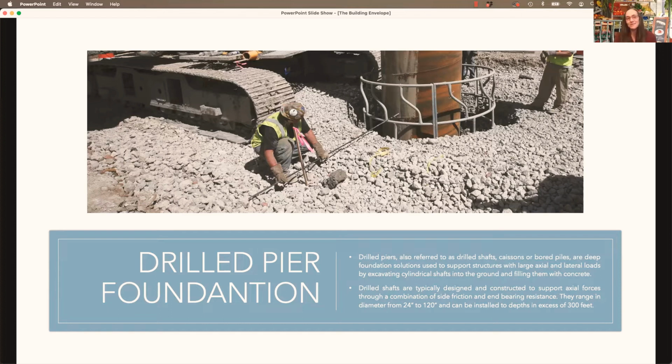I don't know why, but I think they're actually okay. If you float the floor, that just means that you're going to have a framing system on top of the slab that elevates the floor up a little bit higher. Typically, your basement will be a little bit warmer because you can insulate between the concrete slab and the floor surface. So I wouldn't be too concerned about floating floors in basements. But you're right, I do see those in a lot of bentonite areas where there's more shifting because of the fear of the foundation floor cracking.